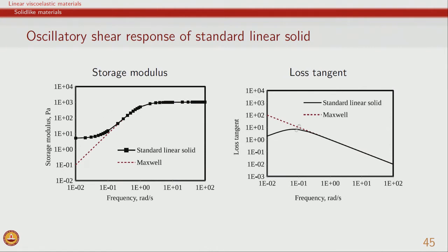When we look at the phase lag, the Maxwell model has an unrealistic phase lag compared to many viscoelastic materials, in the sense that it goes from a very high value to basically 0 as we go from a fluid to a solid-like response, and this is because the Maxwell model has only one relaxation process. Similarly, the standard linear solid model also undergoes a change in phase angle over the same 1 or 2 orders of magnitude change in frequency. However, even at low temperature, low frequency conditions the material is elastic, and therefore the loss tangent is low, then it undergoes a maximum when the viscoelastic response is maximum, and then in the glassy state again the loss tangent is less. So, there is a peak in loss tangent in the case of a material which is a cross linked rubber.